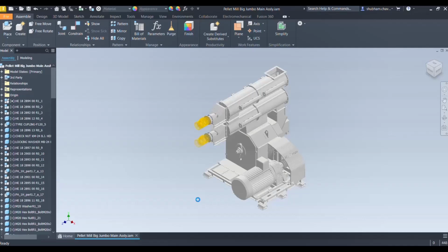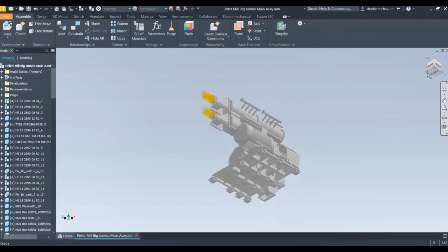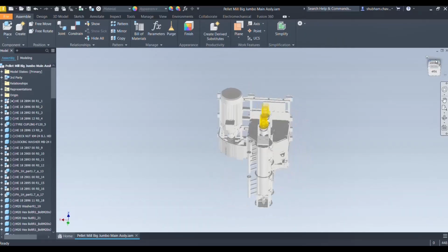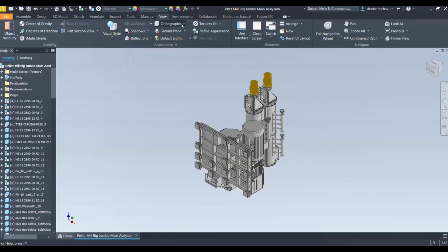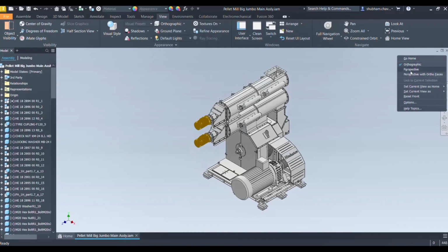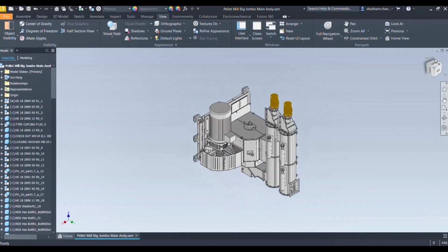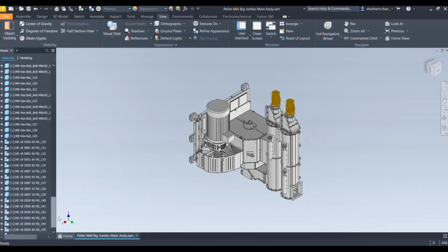As this particular equipment is ready for production, you can generate the bill of material as well. You can manufacture it using the CAD tool wherever you have created that model. Now, the important point is the file size. If it is large, we can import that model within Plant 3D as well, but there is no point in adding that much, because it will increase your drawing size. To eliminate that, we need a simplified version. So let's have a look at how to create a simplified version.